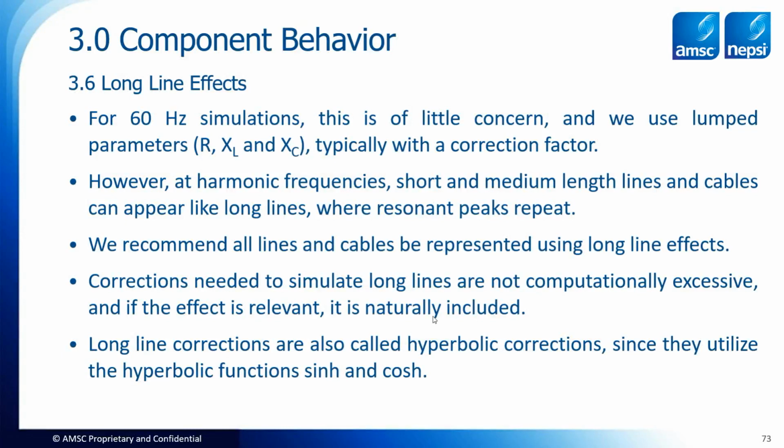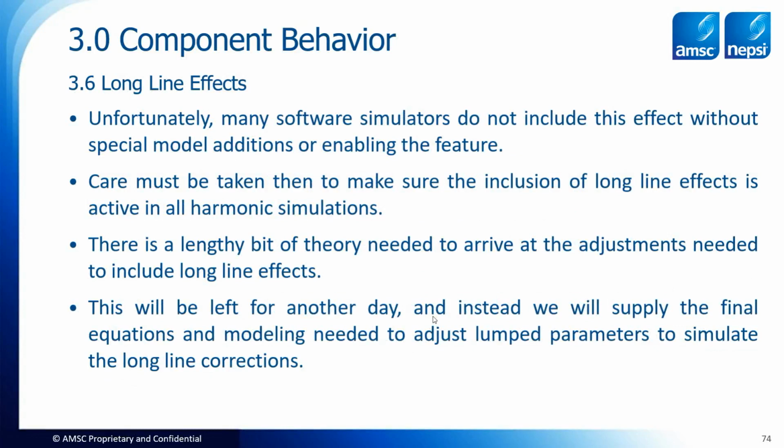Long line corrections are also called hyperbolic corrections, since they utilize the hyperbolic functions sinh and cosh. As I just noted, unfortunately, many software simulators don't include this effect without special model additions or enabling the features. So care must be taken to make sure it is included in your harmonic simulations. There's a lengthy bit of theory to arrive at the adjustments needed to include the effects, and that'll have to be left for another day.